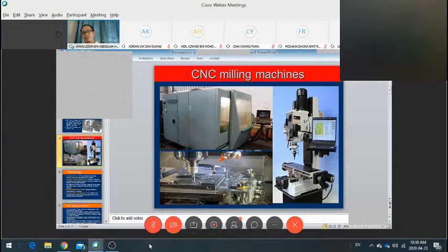Okay, and these motors are controlled by some kind of electronic system, from the program that you input here. So here the keypad, yeah, and the display. The same way for this machine, you have the keypad here, the many different functions here, and this is the display. So the program will be called from here. Then you can execute it. It will control the motor, send the signal, move the table, and then you can do the cutting. So that's how basically a CNC works.